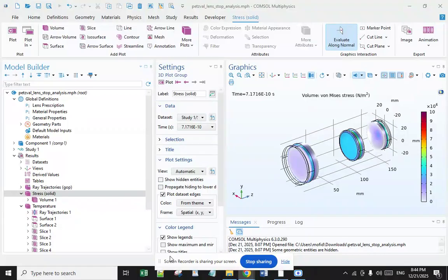Immediately, this presents a clear difference to the earlier diagram. Each spot has grown significantly in size from an initial average RMS (root mean square) spot size of approximately 1 micrometer to almost 50 micrometers in the latest analysis. This suggests the optical performance of the payload may not match initial expectations and in turn mission requirements.